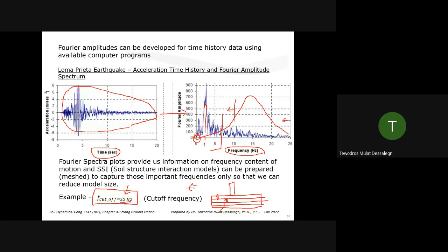It's going to be determined by T is equal to the shear wave velocity divided by 4 times the cutoff frequency. And sometimes this parameter can be 5. So you'll find it, for example, Flux 3D has this formula. This is telling you, okay, the thickness should not be more than this. If it's more than this, the wave is not propagating.